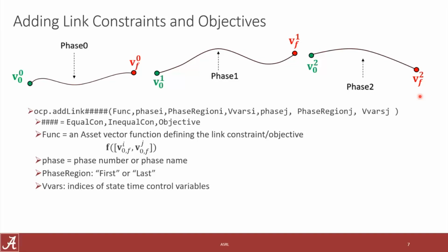Yep. There's nothing forcing the phases that you add to an optimal control problem to be continuous unless you constrain them as such. So you could even have a target phase in some orbit using some dynamics, and then a launch vehicle with different dynamics, and then that launch vehicle could deploy a low thrust spacecraft that you then patch back to your target, but the launch vehicle never has to touch.